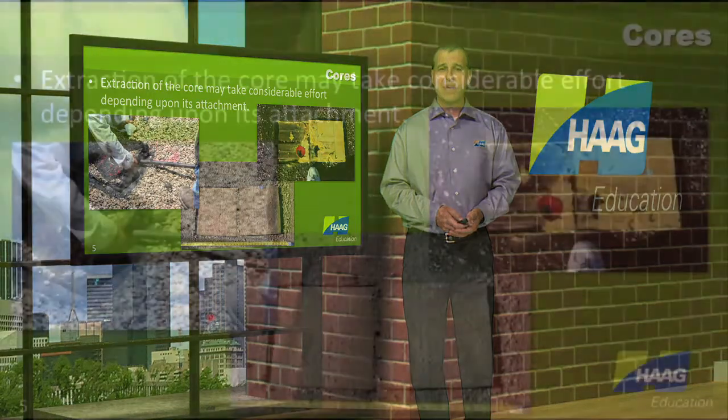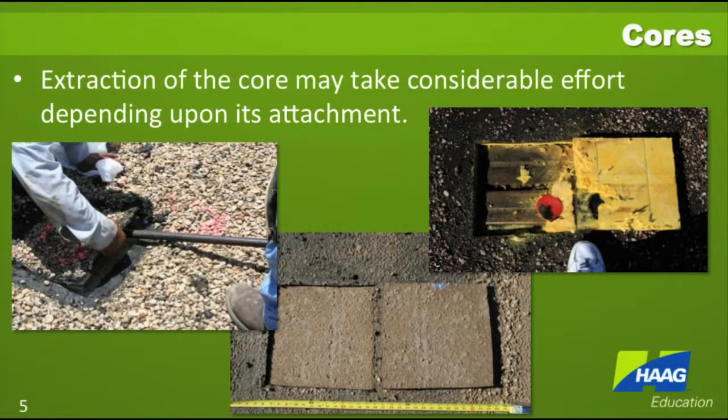Once the cut is made, you have to extract it, and at that point you can check to see how many roof layers are in place, is there any moisture in the insulation, or any visible fractures or punctures in the roof system. In the photograph on the right, we're seeing that we've exposed down to the metal deck. And so it's good to go all the way down to the deck level and see just how many layers are in place on your given roof.